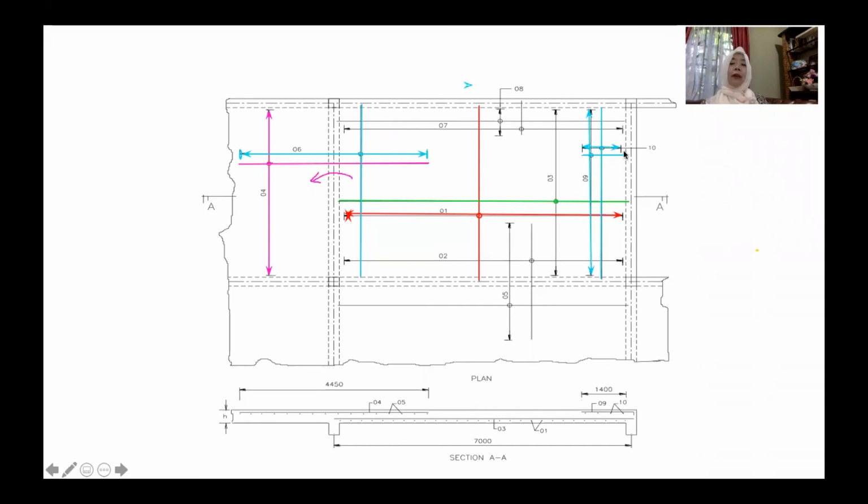Okay, so we complete this section here and here. How about this section? Yeah, this way, LX, at the LX direction. So remember, we design moment here. We got 0.5. Yeah? 0.5, again, we need to provide steel from here to here.